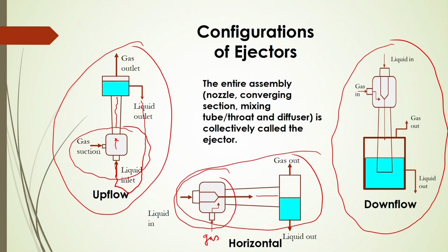At a certain operation you will see some bubbles that are not going upward against the liquid momentum, or some bubbles that are not going downward because of the higher buoyancy effect. So there will be a balance of buoyancy effects and downward liquid movement, by which you can get a long residence time of the bubbles at that particular location.